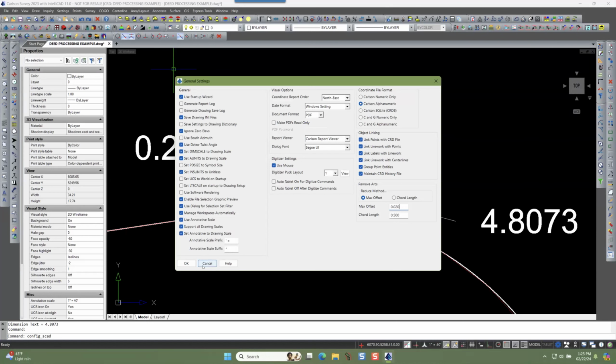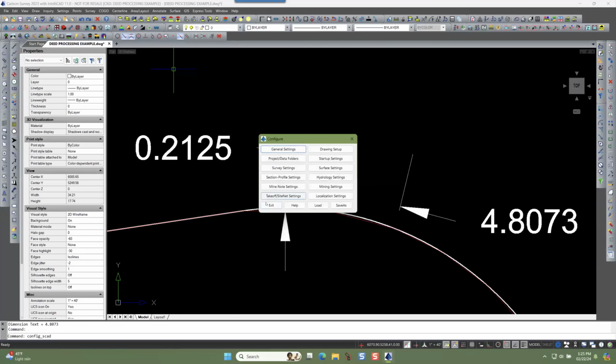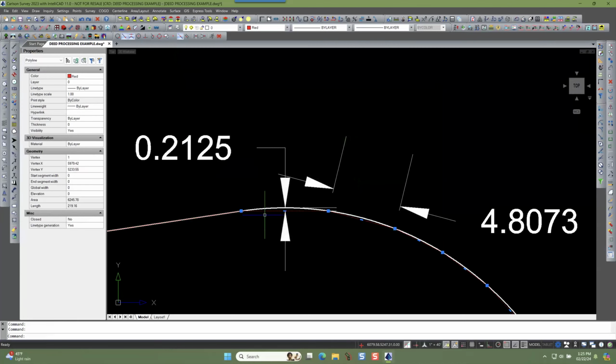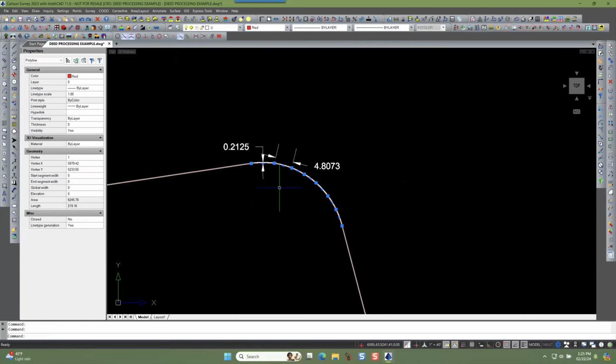Because when it converts that into a 3D polyline that you're going to use to do your terrain modeling, every one of these vertices, all of the endpoints of all those little chorded segments, are going to be the corner of a triangle, and usually probably 3 or 4 triangles.